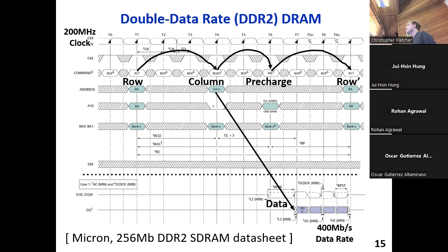That's exactly right. The primary way that we can achieve pipeline parallelism in a DRAM is by arranging accesses so that different banks are looked up concurrently. How your data is mapped otherwise is less important. And so the DRAM manufacturers recognized this and said, here's a bunch of address bits that you can drive, and we're not going to tell you anything about their semantics because it doesn't really matter. However you decide to use these address bits is up to you.